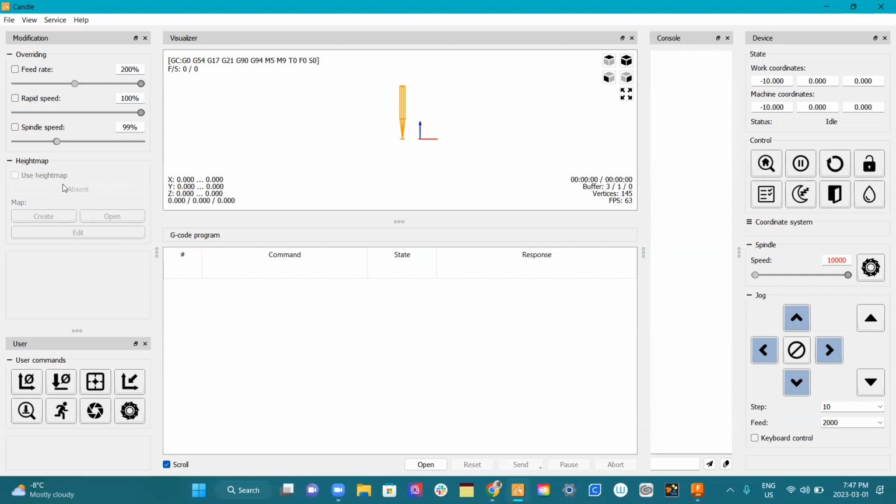Caveat is that the wood is not conductive. So this works on my, okay, I have to do it on sheet metal. This metal is 0.4 millimeters thick, right? It's very, very thin. And so if I want to cut halfway down in order to make a plate or something, I don't want to go all the way through it. And it's also metal, it's bent, you know? So I do this setup because I want that to be flat along the whole surface of the thing and have basically all those lines be the same depth into it.